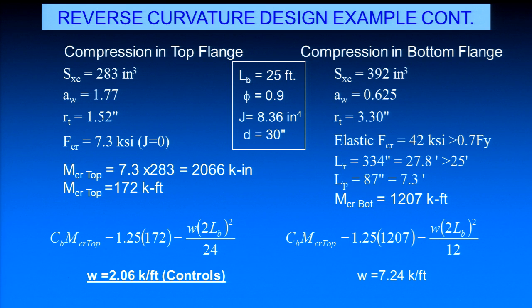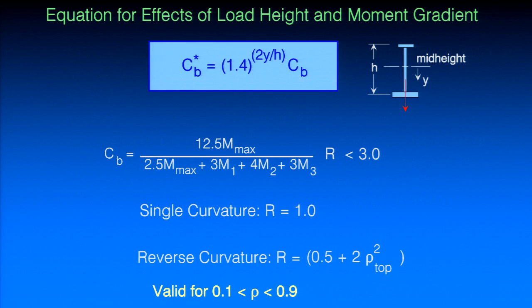We had actually, I think it was in the 13th edition, this modification was actually included in section F2 of AISC. And essentially all it did was cause a whole bunch of questions. People didn't know how to apply it. And part of it was we had to make some changes, and it kind of dumbed down the equation, and it didn't work very well. So what we've done since is we essentially say in section F2 that, you know, for singly symmetric sections you should go and do more of a rational analysis. A rational analysis is going back to the commentary and reading and seeing this modification. Okay, so you can still go to the commentary and actually get that.